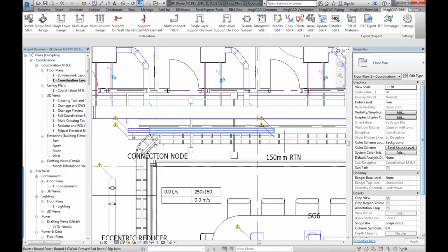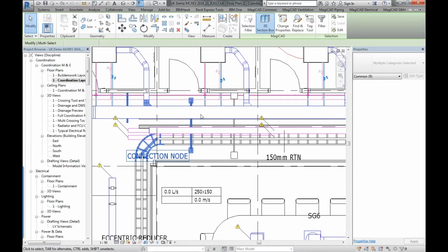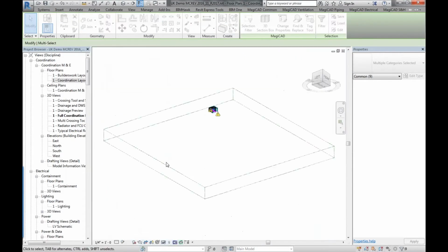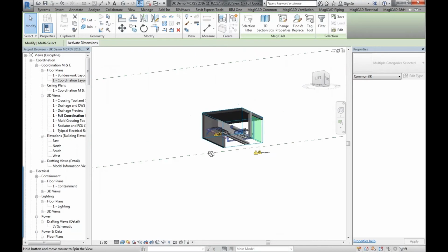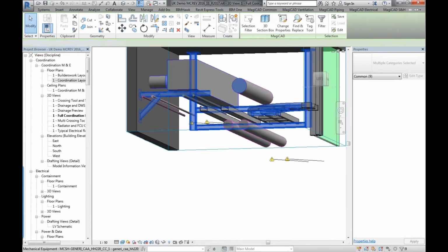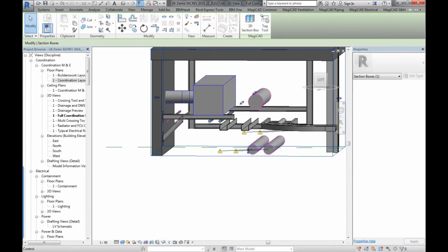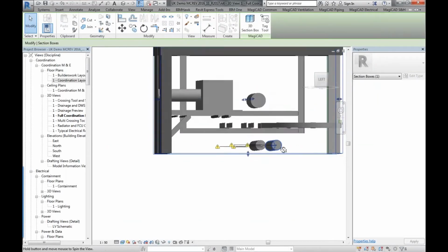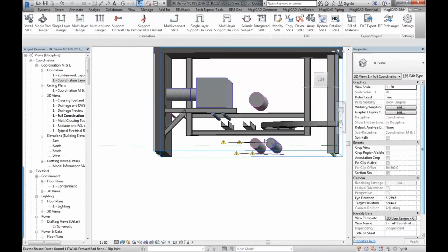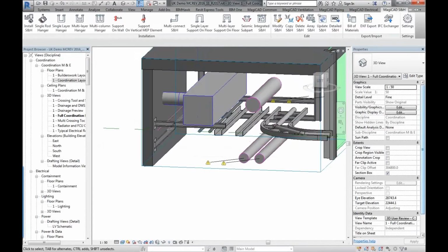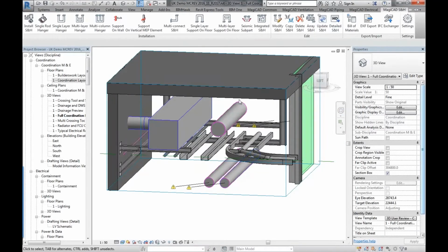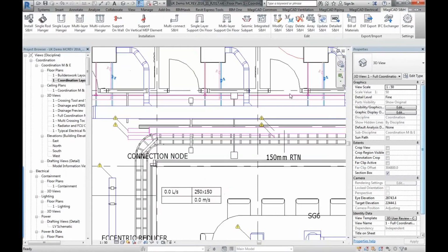There's one thing left that I haven't shown yet, which is showing integrated hangers. So what you can do, you can build hangers on top of hangers. For instance, in this case here, we've got a hanger already pre-made, but now I have these two ducts that are sitting below it that have been introduced into the project later. So I may wish to support those off that hanger that already exists, rather than supporting this straight from the slab again.